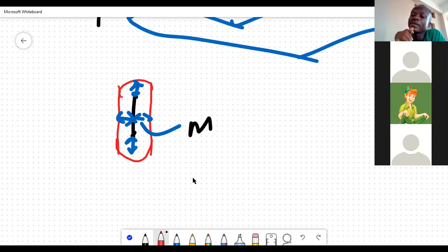Let's say we are digging a foundation for a building, and you need working space. So meaning that if you are going to dig a column of, let's say, 200 square mm, you have to dig 400 square mm so that you cut a working space. That working space will serve as your buffer. Is it something like the buffer that you are talking about? Yes, brilliant, Benjamin. That is exactly what it is.